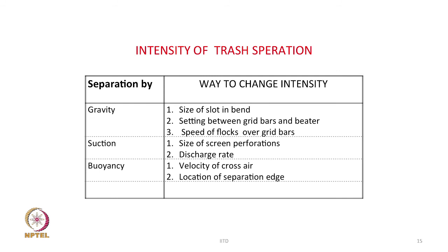Then the speed over the grid bars, that is the speed at which the particles are hurled over the grid bar, also will matter. So, gravity action can depend upon these factors. The other factors could be the angle at which the grid bars are placed also. So, that also can matter.